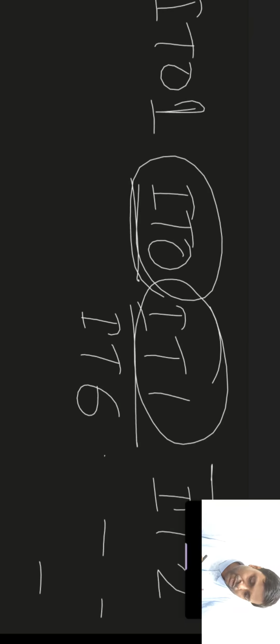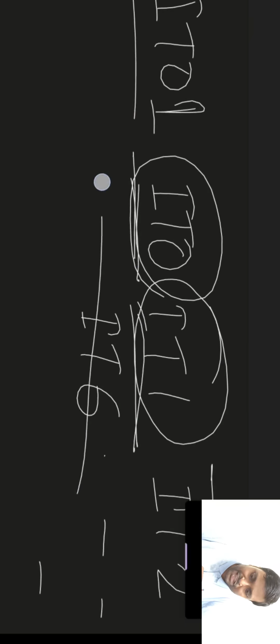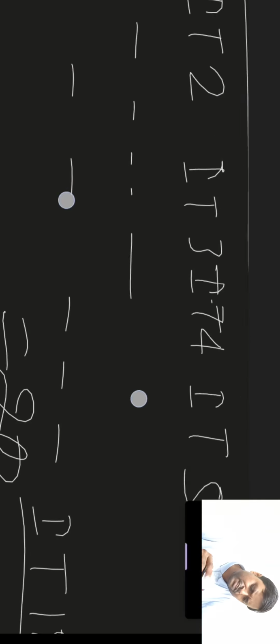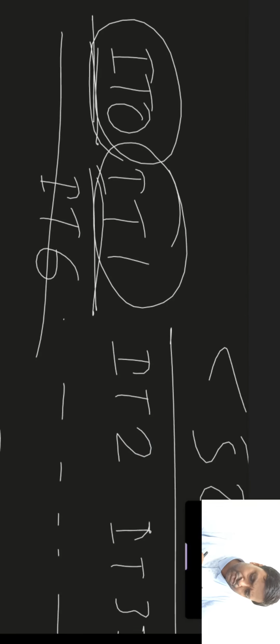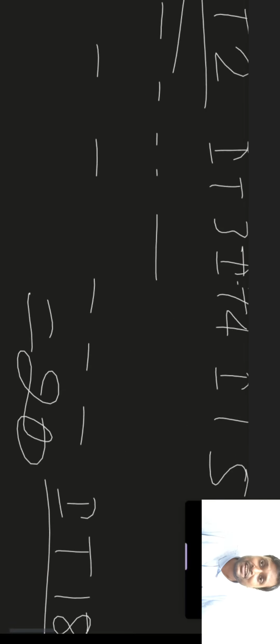So IT 01, IT 0, then IT 1 to IT 18, are all together 20 grades of standard tolerance for basic size up to 500 mm. So what do IT 01, IT 0, IT 1, IT 2 and so on up to IT 18 imply? How do they represent the value of tolerance? Now we will discuss this point.